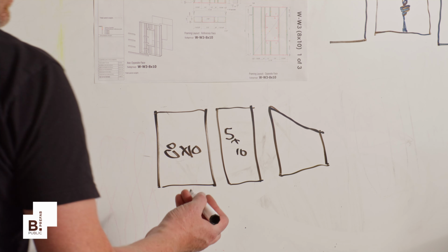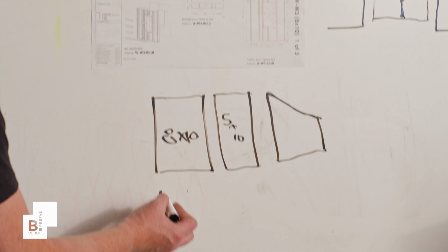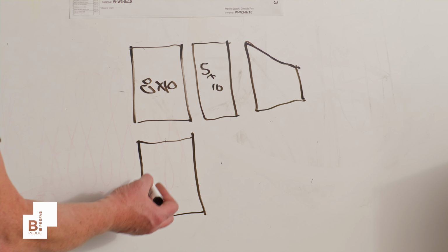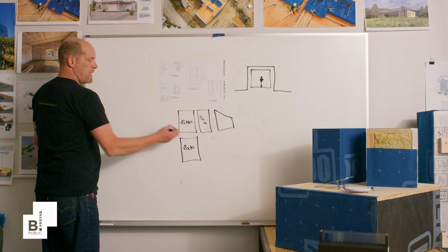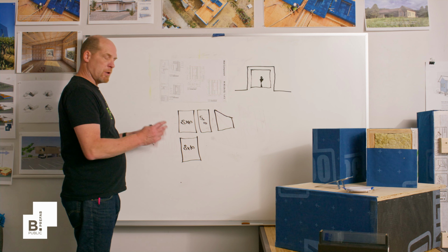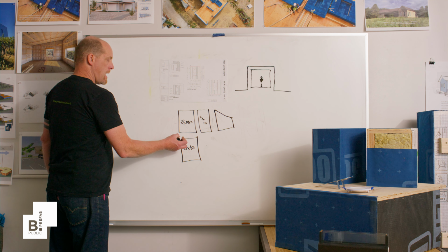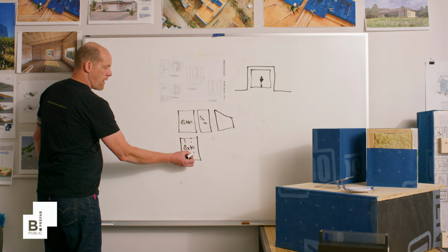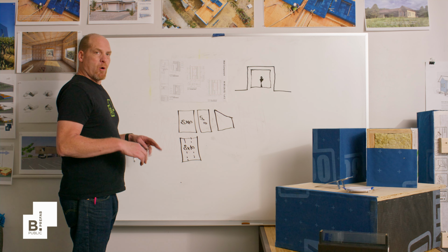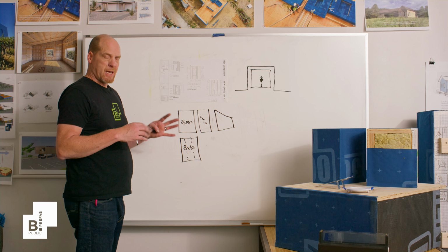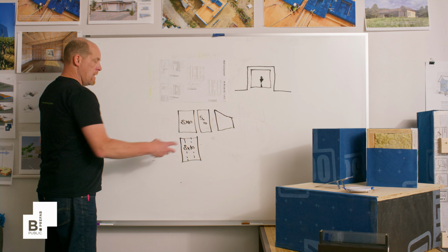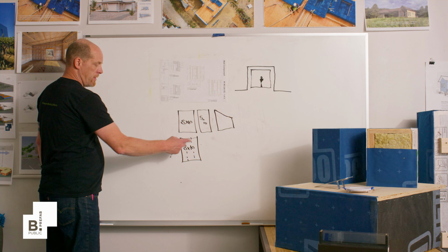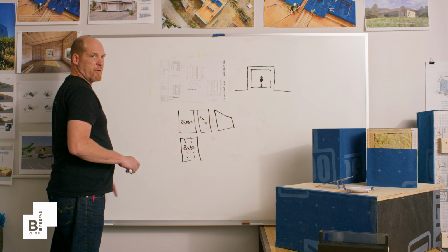The other version of it would be, say it's a custom panel that might have the exact same size as a standard panel, but the structural requirements or loads on that panel are specific, and we might need additional framing in that member, or potentially the sheathing. It has a significant shear load, where the technical qualities of that custom panel are the thing that's making it custom, not necessarily the dimension. So those are the different versions of custom panels.